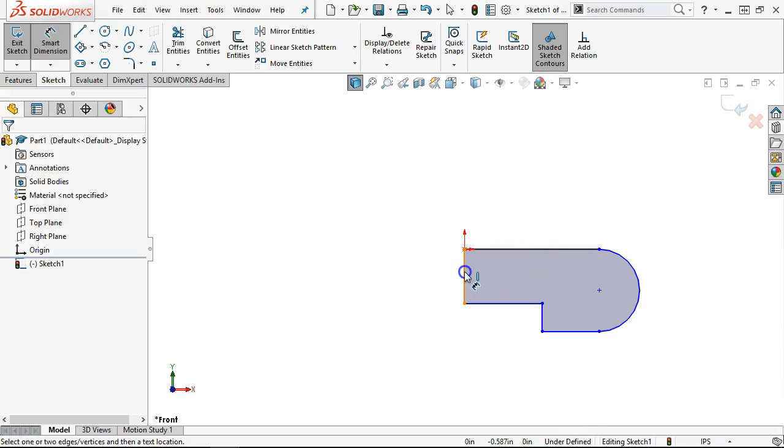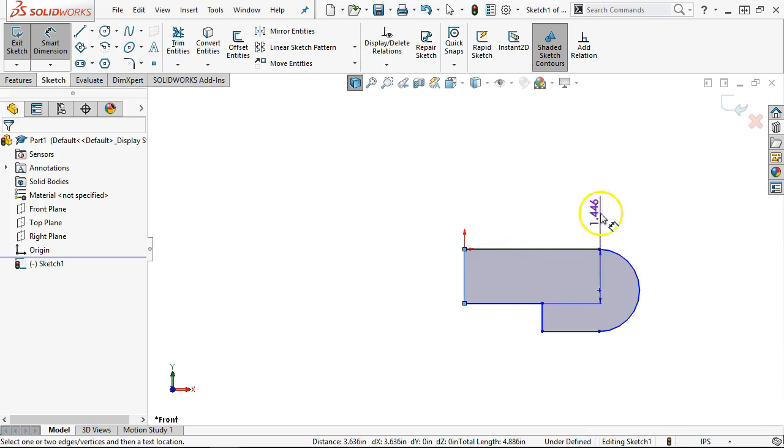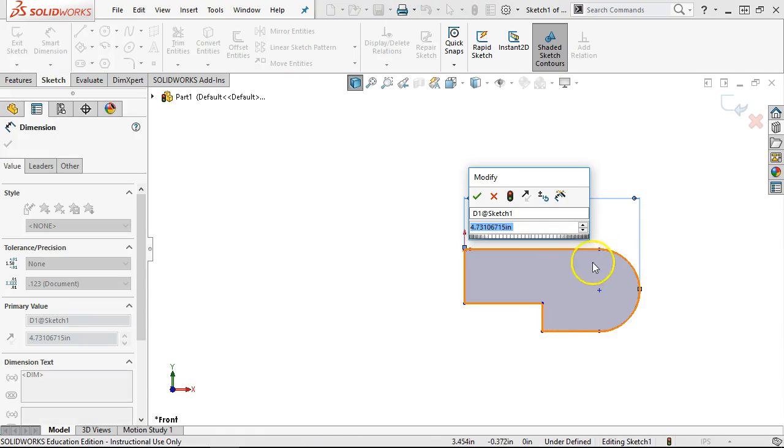The 4.125 is an overall, and I didn't hold down the shift button, so let's go ahead and back up. I'll hold down shift, and when I select the arc, notice that it jumps to that max condition. All right, if there was another side of the arc and I was coming to the back side, I would get the min condition.